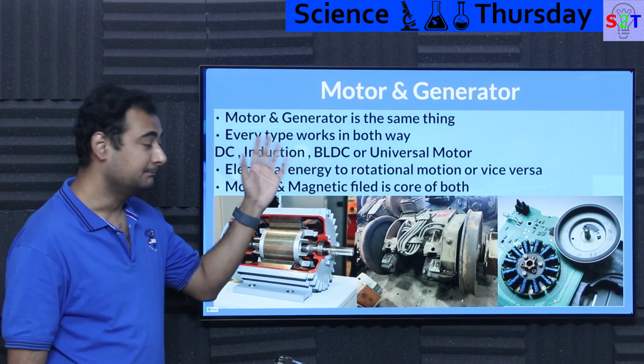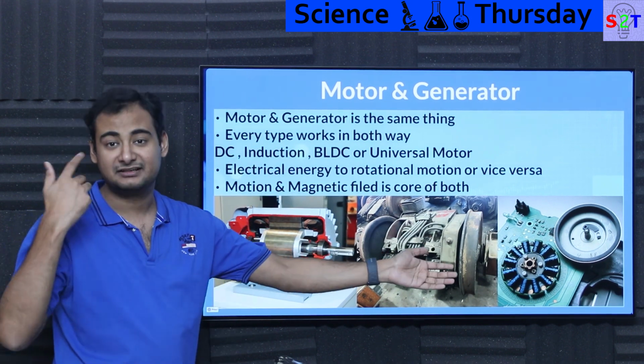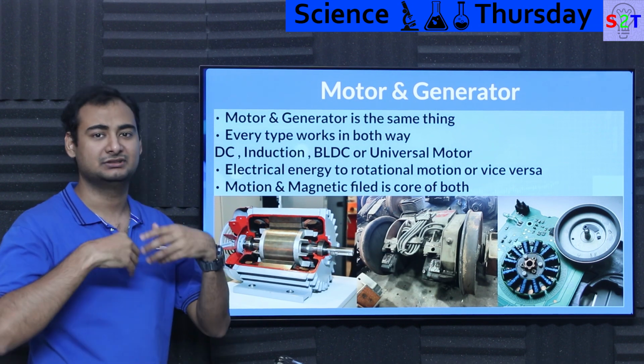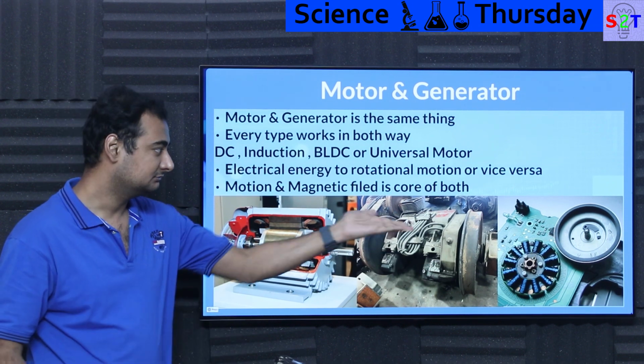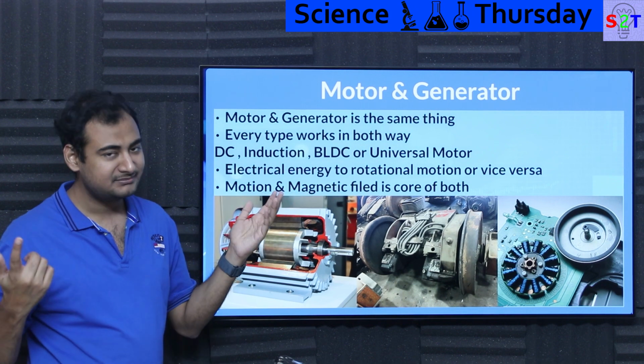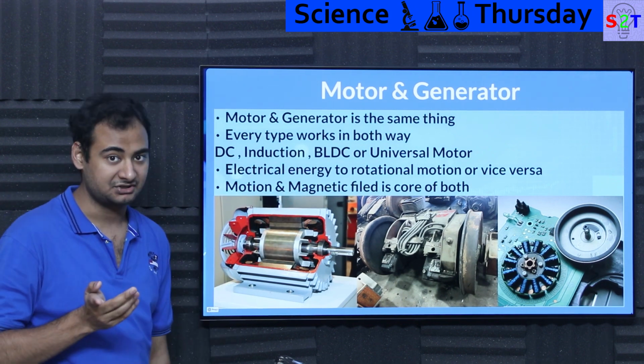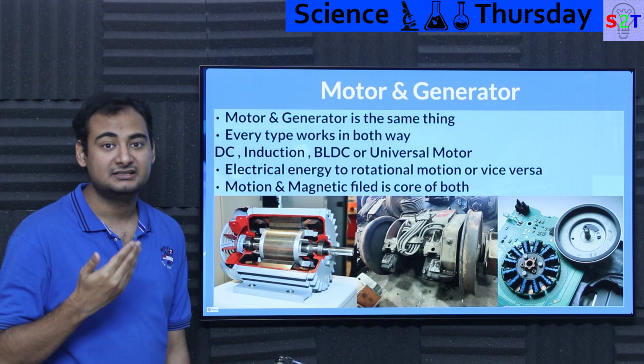Even this puppy, the BLDC, it has magnets, so most people can inherently think about it. You have magnet, you have motion, you get energy out of the coils. So that does work. The universal motor does not have a magnet, still will work, but it does have brushes. That has some consequences. And some designs do require excitation.